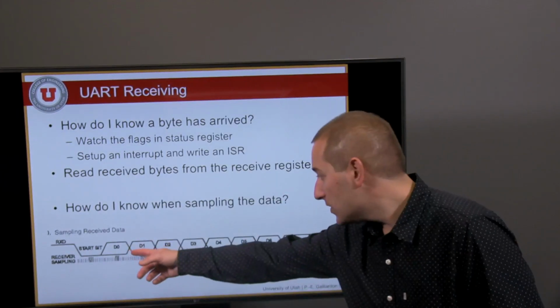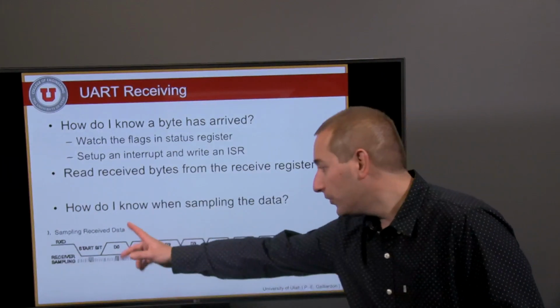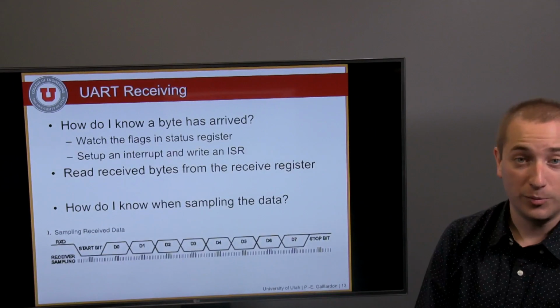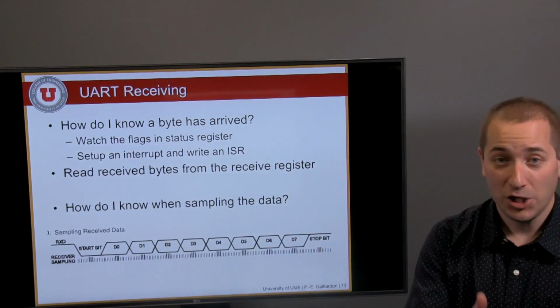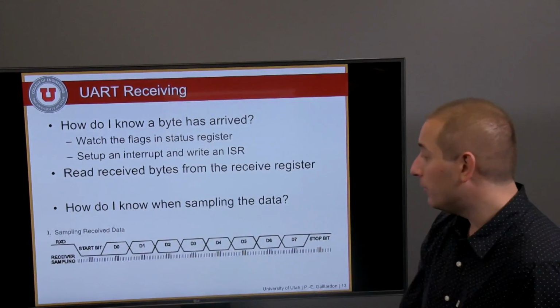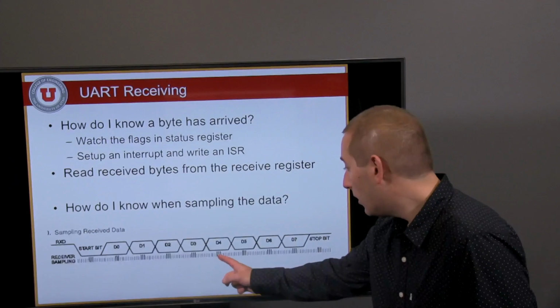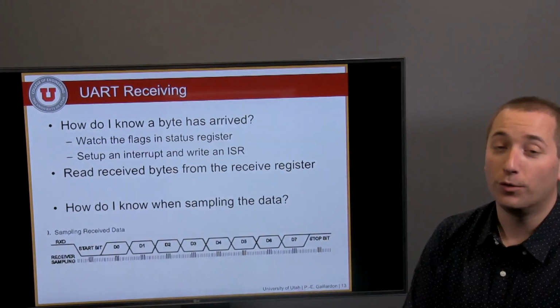The receiver is going to oversample the baud rate, and start counting at the beginning of the start bit, and the goal of this oversampling is to latch the data more or less in the middle of a clock period. That way, the error is only the value of one period of the oversampling rate.